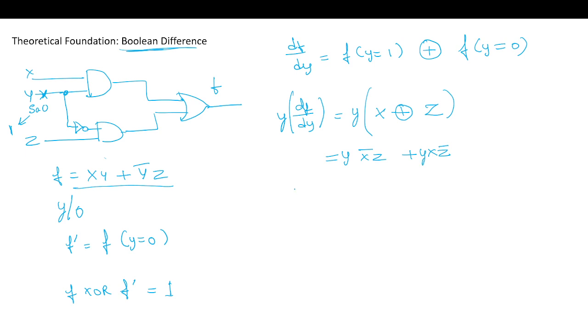So the test pattern, if I consider x bar yz plus xy z bar, for xyz will be 0 1 1 or 1 1 0.